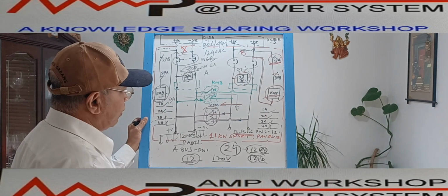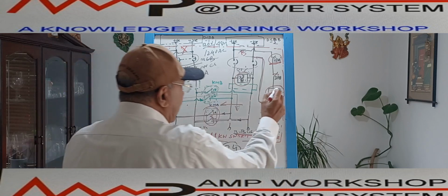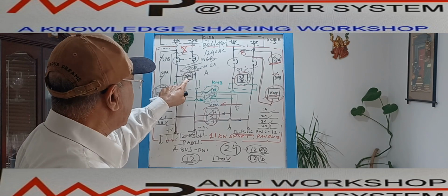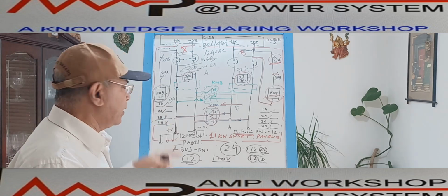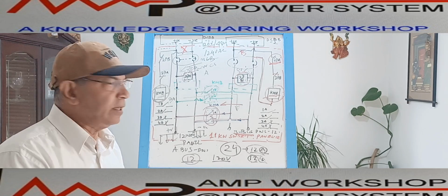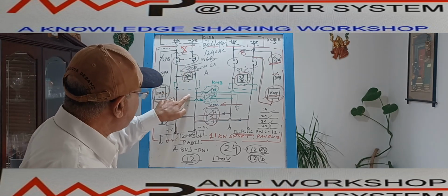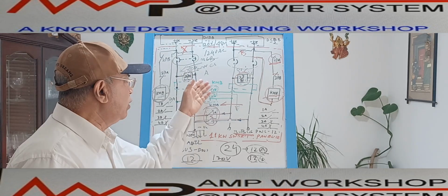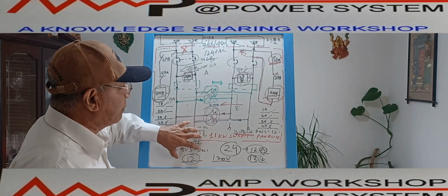Now, a consideration over here: why are we using KMB and KMA contactors? Because if we use an auxiliary relay like an under voltage relay, all the auxiliary relay contact ratings are very low. It is a maximum 5 ampere rating, and we cannot use that in the power circuit. This is the power circuit actually, this is the main power. This main control power is flowing, which may be 50 ampere or 25 or 30 ampere depending on the VA capacity of these 12 number panels.